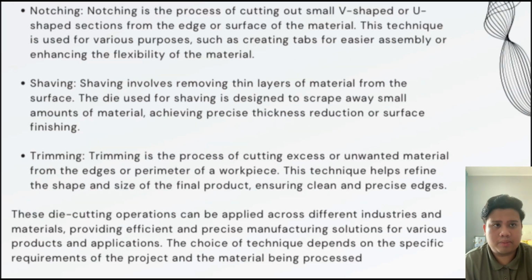Notching. Notching is the process of cutting a small V-shape or U-shape section from the edge or surface of the material. This technique is used for various purposes such as creating tabs for easier assembly or enhancing the flexibility of the material. Shaving. Shaving involves removing thin layers of material from the surface.